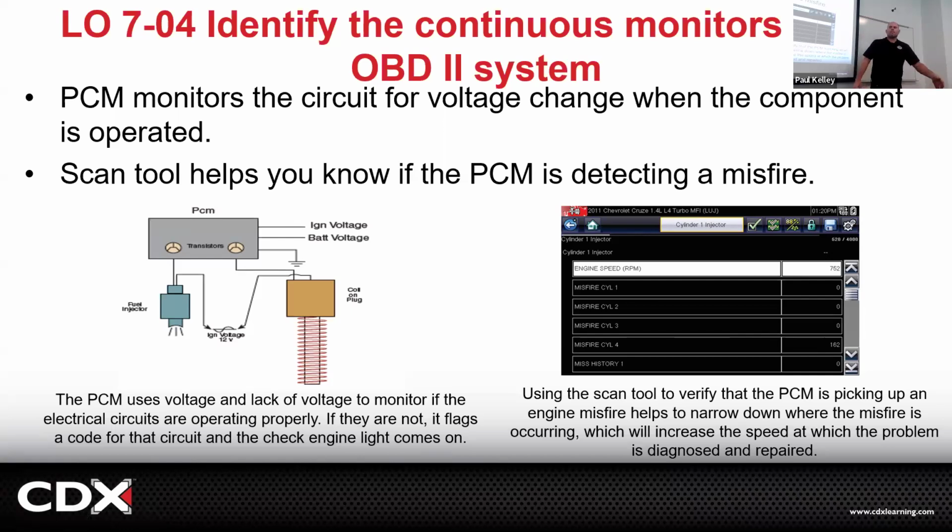So in the onboard diagnostic system, it does some level of self-diagnosis. So you might get a code, injector circuit number 1 open or short to ground. And you're like, well, where's the open? The system doesn't know. It doesn't have the ability to know. It just knows when it fires that injector, it should get this reading, but it didn't get that reading. So it knows that there's either an open or a short to ground. Make sense? Exactly the reading that it should get, well, it depends. It depends on what the internal resistance is after that transistor, so I'm giving you a generic. It's programmed to say, when I fire the injector, I should get this voltage. But if I didn't get this voltage, that means there's a problem in the circuit.